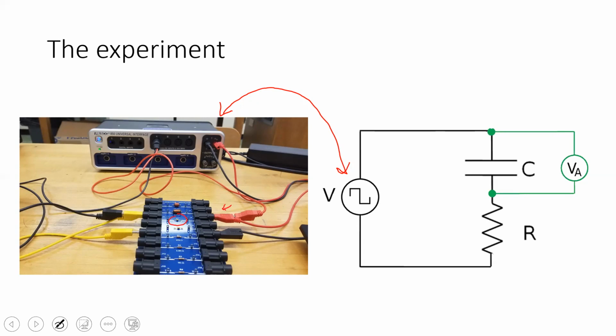I have plugged it in to this capacitor here. It's a very tiny device. It's labeled as 3,900 picofarads. Then, according to my schematic, I'm going to come out of the capacitor and go into a resistor. So that's what this yellow cord right here is doing. It's coming out of the capacitor and into a resistor.